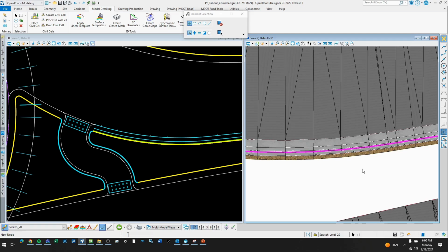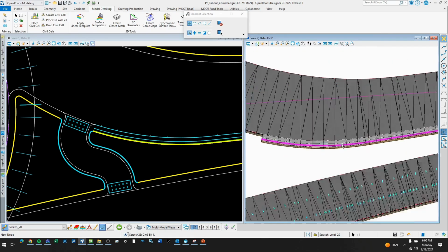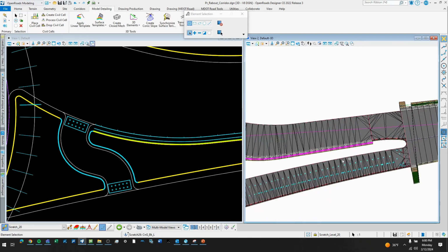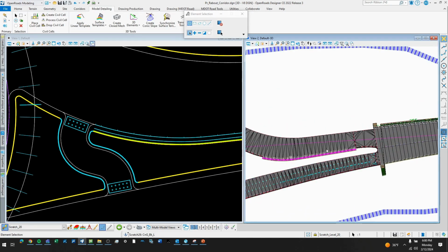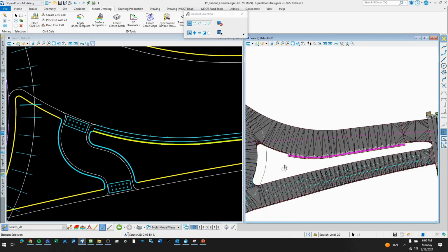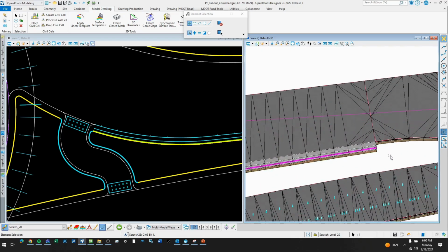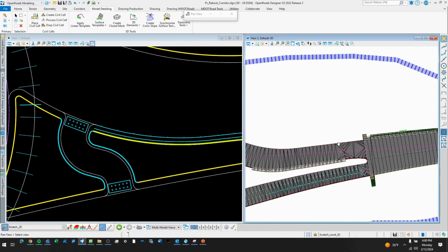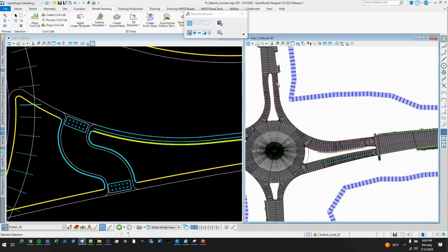You can click it and isolate it. It's this one right there. So you can grab all these and make a terrain from that, and then do another surface template, and that's just like a concrete, whatever you guys end up doing for your inside splitter island. That'll fill that gap.